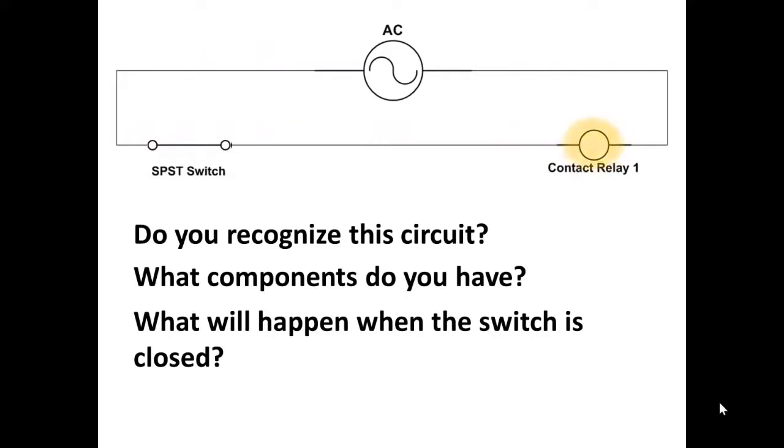Now I show the relay going off as the current reverses, but remember that this is 60 cycles per second, which means that 120 times a second the voltage goes to zero and then keeps on going right over to the opposite polarity. So the relay doesn't have time to de-energize, even though I show it de-energizing in the diagram.